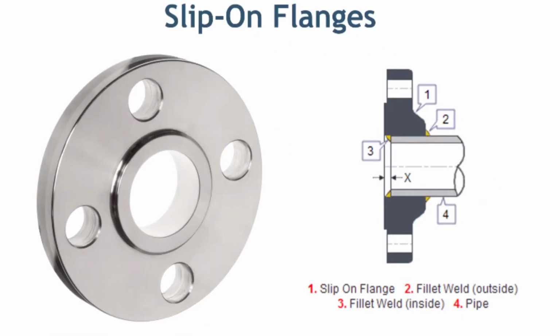The next type of flange is a slip-on flange. Slip-on flange, as the name means, is a flange slipping on the pipe or fitting when connecting. Slip-on flange is essentially a ring that is placed over the pipe end, with the flange face extending from the end of the pipe by enough distance to apply a weld bead on the inside diameter. Slip-on flange is connected to the pipe by two welds, one on the back side of the flange and one on the inside of the flange.